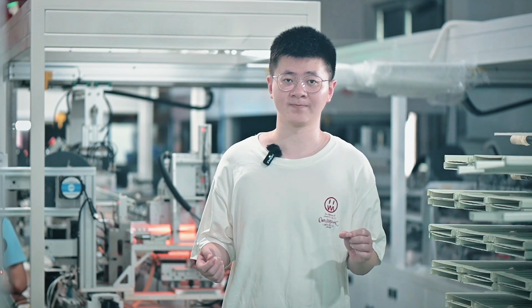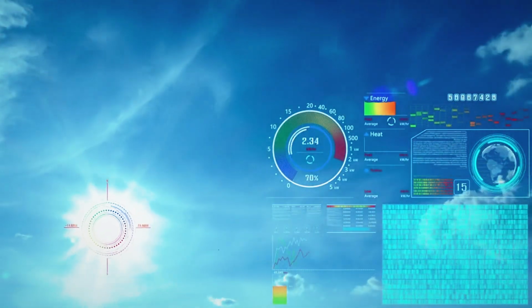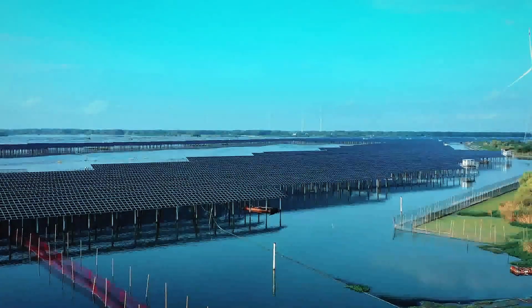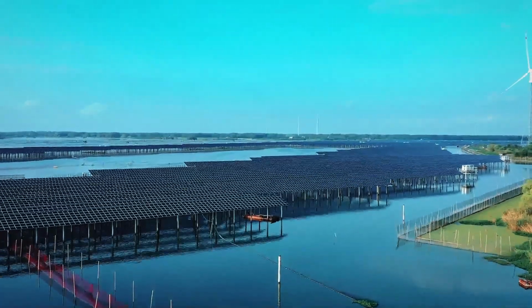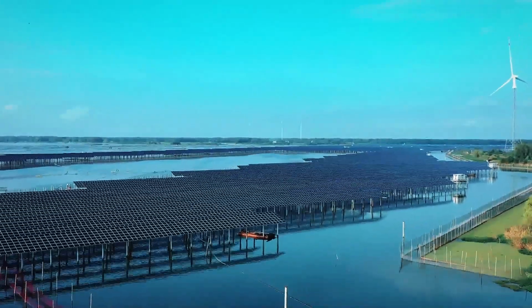For example, parallel solar panels operate independently of each other. They are best suited for partial light situations or when some of your panels may be in shadow for part of the day. Also, series wiring is better suited for sunny open spaces where there is nothing to block the sun's rays.